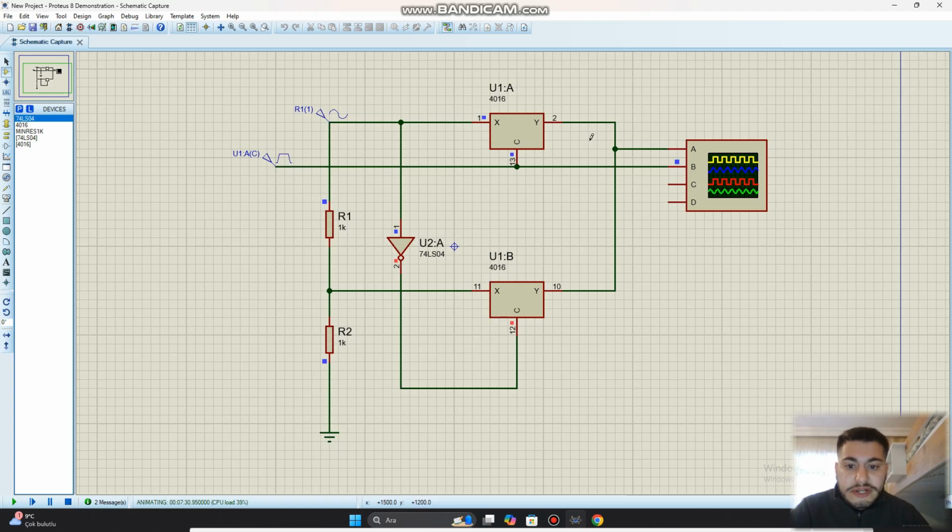The signal source generates the carrier signal. This signal is usually a sine or cosine wave, and I used a sine wave in the circuit. At the output, an amplitude modulated carrier signal is obtained. This signal can be transmitted via an antenna or given as an input to another circuit.